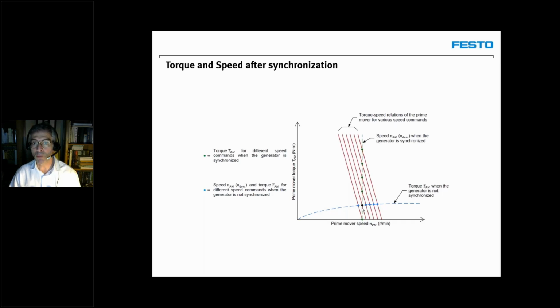So as we put more mechanical power in the rotor, this will increase the mechanical torque on the rotor without changing speed. But as you know, the mechanical power is the product of the speed and the torque. So if the speed remains constant, but I increase the torque, it means that I am putting more mechanical power on my generator, which in turn will be converted to more electrical energy.